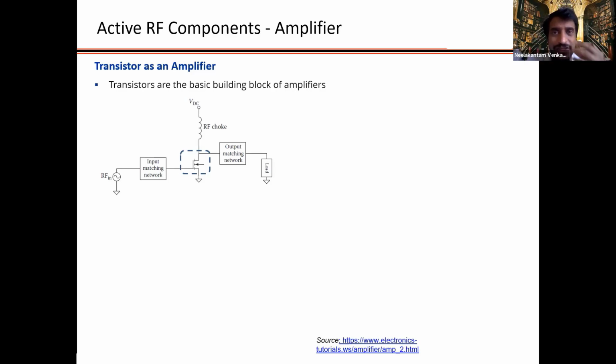So essentially you're going to tap that feature of the transistor, but build something over it. The transistor becomes the building block, but outside the transistor building block, you have this DC supply. It is this DC power that is connected to make the RF power come out, because this guy, the RF in, the power is very low.